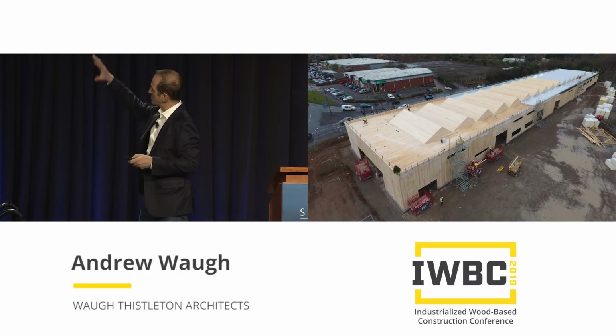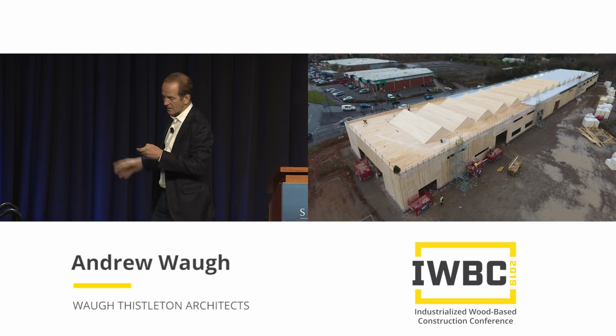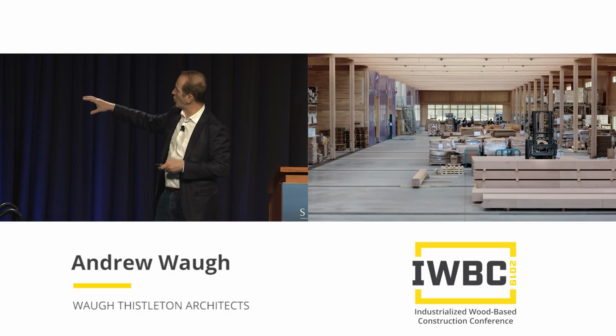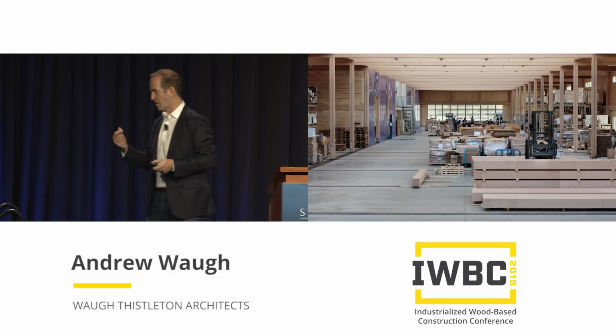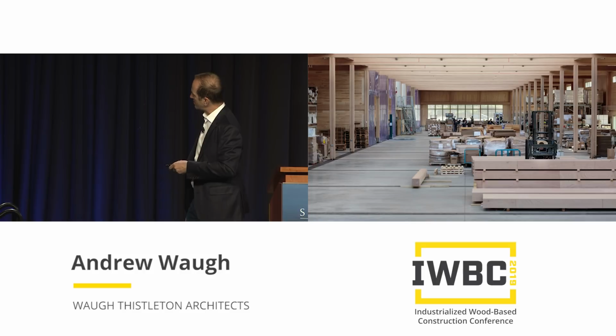So you have this large external softwood CLT shell, if you like. And then inside, in the factory floor, you have a hardwood LVL beam and post system. And the tolerance on this is less than 1 millimeter. So I don't know, that's about a thumbnail in Imperial. And you can see the beams here of the LVL.